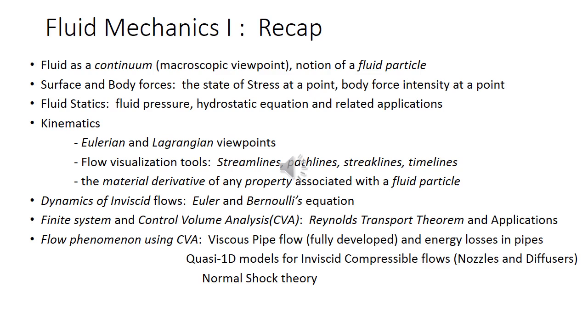If you take this holistic viewpoint, this is also known as the Eulerian viewpoint or the field viewpoint, and you describe the velocity field, and you say that this is how velocity varies in space and time. The meaning is that if you are at a fixed location, then as the fluid particles arrive at that point at different instants of time, what are their velocities? Or if you fix yourself in time, then at different points, if you visit at a given time instant, like a camera snapshot of the fluid, then those velocity variations you can readily express from the Eulerian viewpoint. So velocity field itself is a Eulerian variable. That is the essential idea that we had learned from our earlier course.